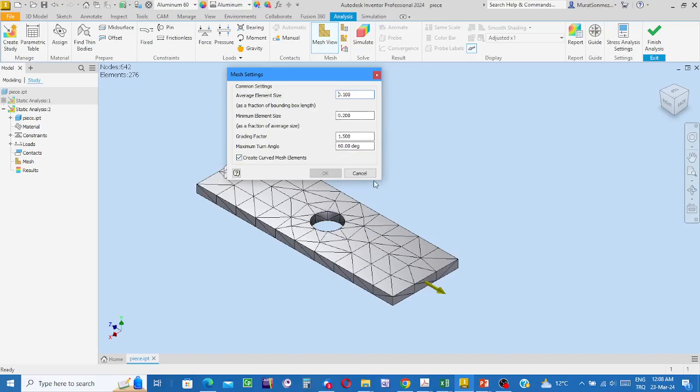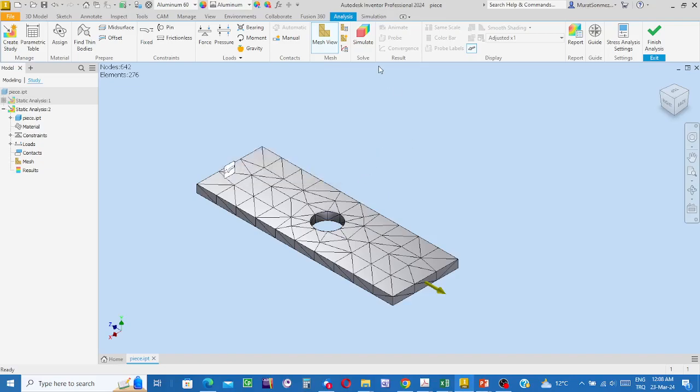Okay, so 15, and writing the local mesh control technique, writing or selecting the mesh size. Well, I'm going to use a smaller size. Say that not 15 millimeters. Here it is not percentage. You see element size, directly right. It is size value, not a fraction.